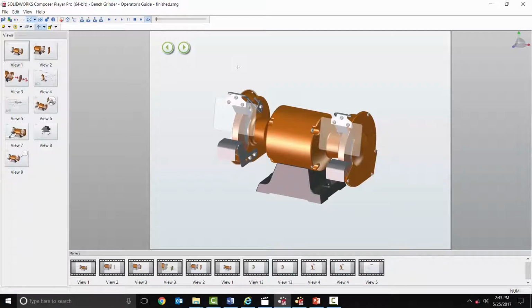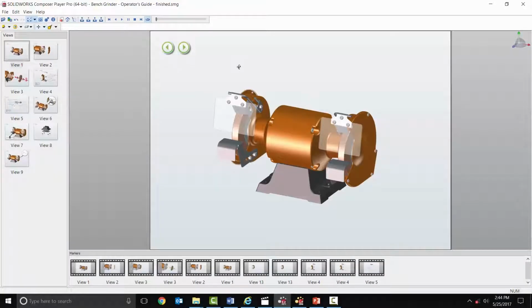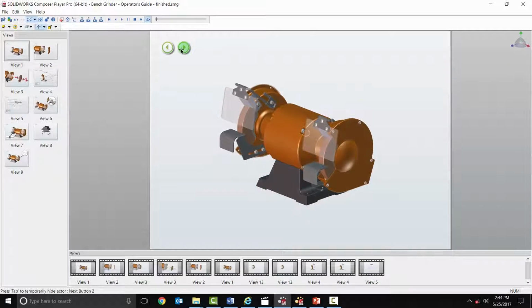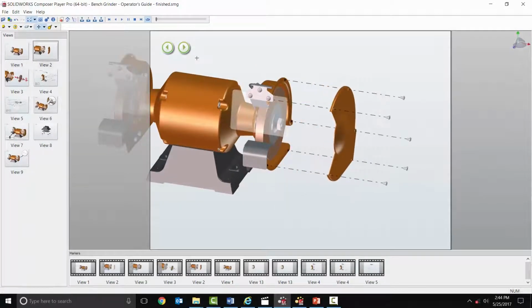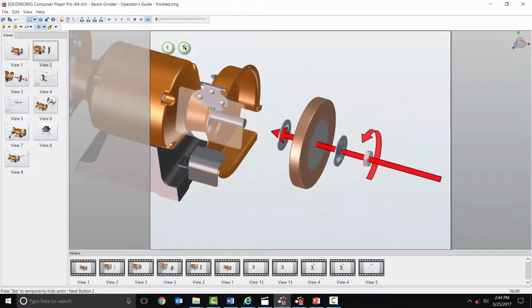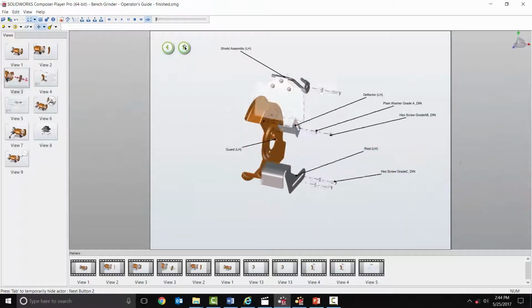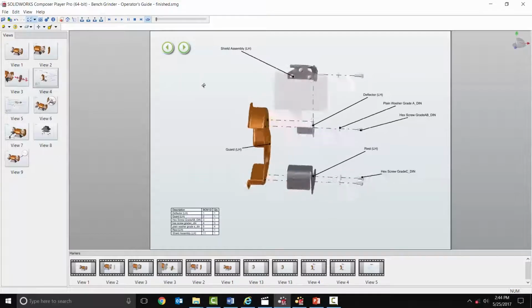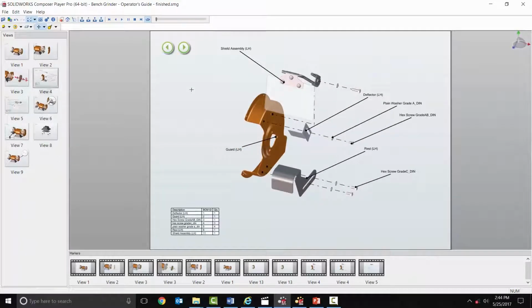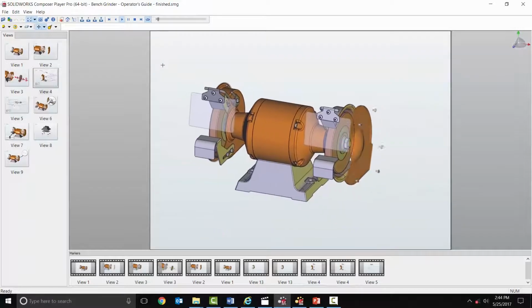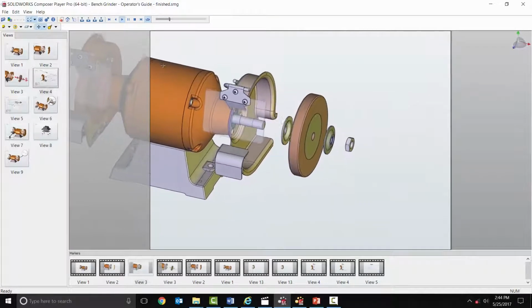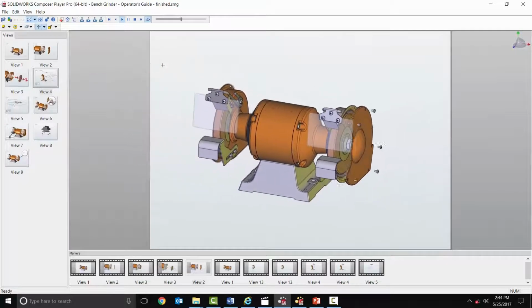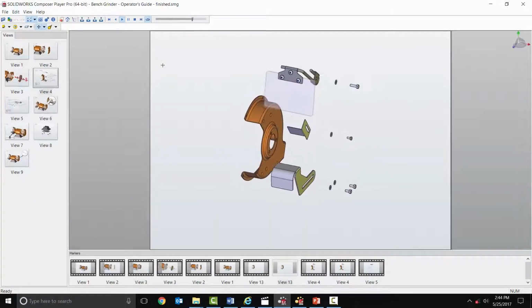And finally, one other piece of content you can generate from Composer are interactive files. These are typically in use for things like assembly and manufacturing instructions on the shop floor. And so they can actually be interactive, so you can see you can have assembly procedure steps embedded in them, as you see here. And these are also interactive, so you can rotate, zoom, pan, take internals, or even embed a video player in here as well, so that someone actually can see what's going on at any given step inside the assembly process.